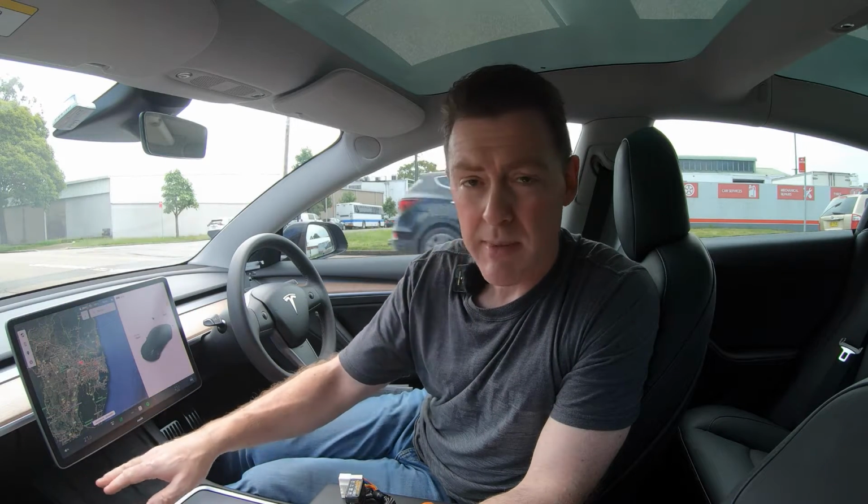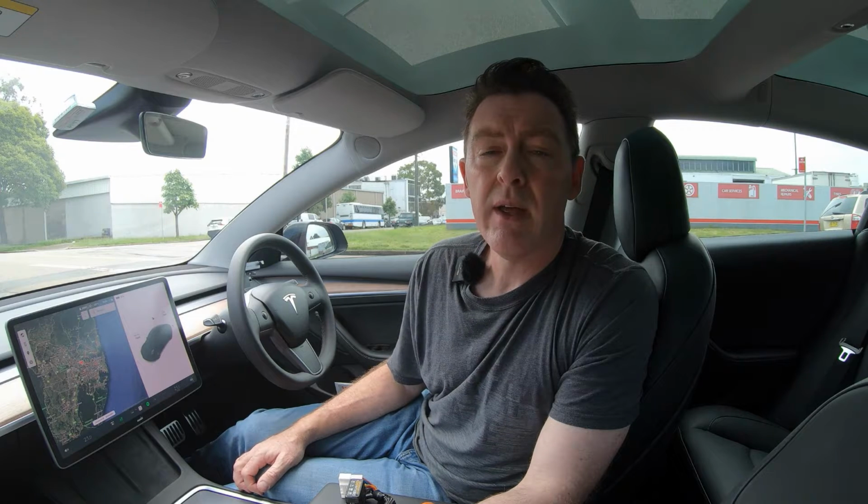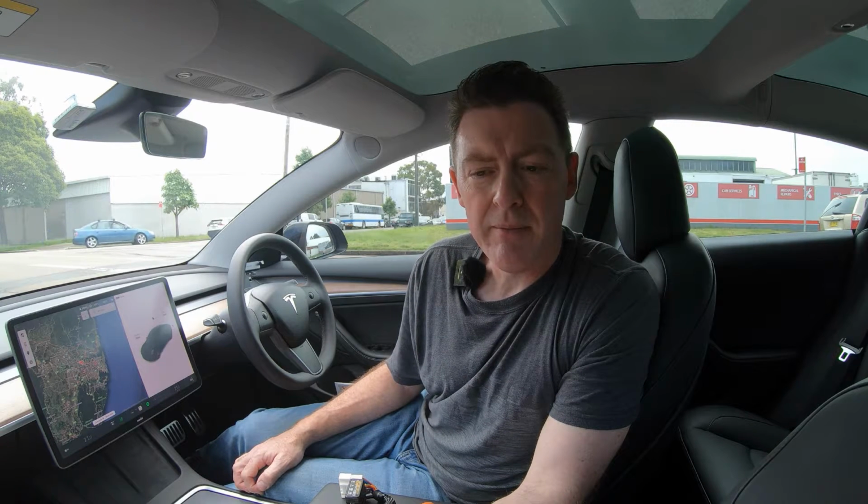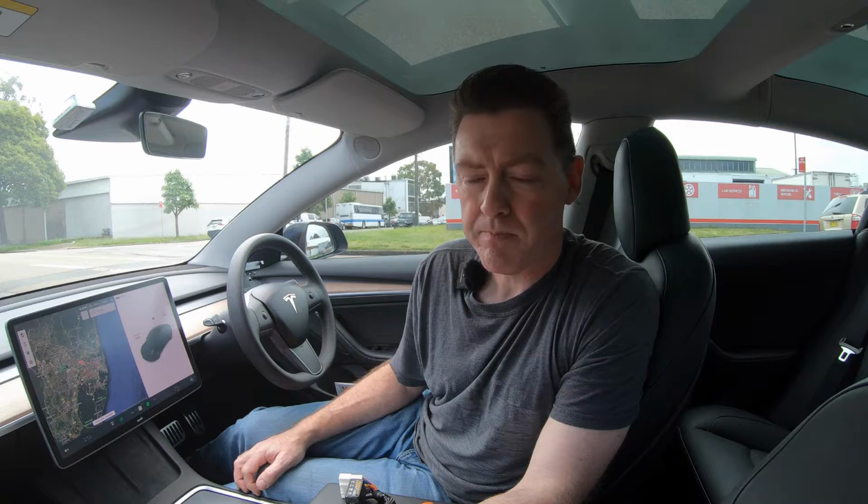So the first part of it is an app on the phone. Then the second part of it is a harness adapter in the car that allows you to tap into the vehicle's driveline CAN bus system or chassis CAN bus system that you can't normally access through the other OBD port under the dashboard. And you then have an OBD2 adapter, a Bluetooth adapter that allows communication with your phone, wireless communication.